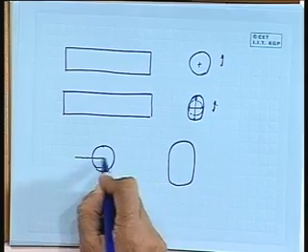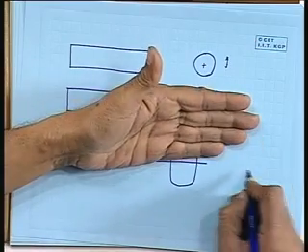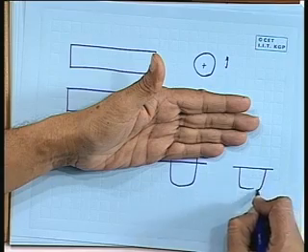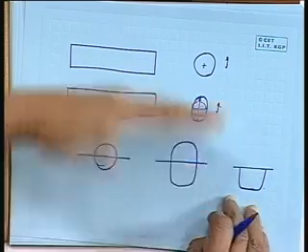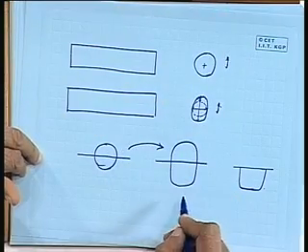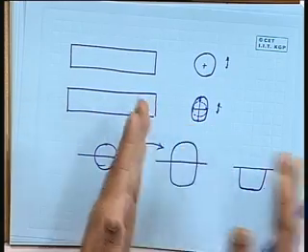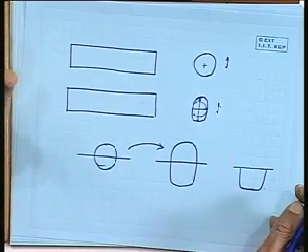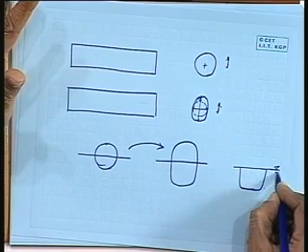Now, if you cut it here, then you take 1/2 of it, and this 1/2 we say is same as the midship section. Okay. So, you are taking a symmetrical section, you are transforming this mathematically to this, and whatever added mass coefficient you are getting here, you are considering that for a similar ship section it will be half of that, because I am considering half section here, and you put the water line here,